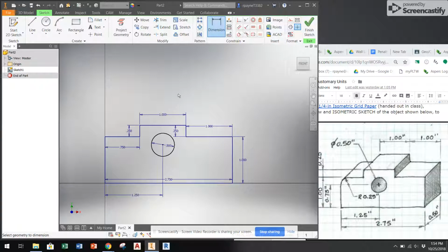All right, it's placed. And then dimension again. And so the height now I know needs to be from the bottom edge to here needs to be 0.75. So I click on the edge and the center again. And now it's not the right number, it's 0.829, which is not correct. So again, I place it and I type in 0.75, I hit enter, and I see the circle move down to where it needs to go.